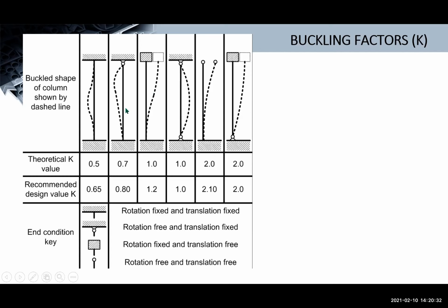If you notice, these are like the elastic curve of a beam. If you make the shape of the column horizontal, right? For a fixed support, if you remember drawing the elastic curve, it is straight at this part. And then it deflects afterwards because there is no rotation at a fixed support. So you can also visualize the buckling. And it is times 0.5 because the length we consider is the length that buckled. So, this is your 0.5.